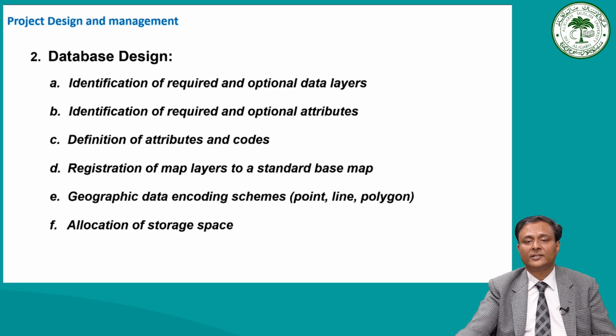The next can be the registration of map layers to a standard base map. In all the spatial information analysis, we try to bring all the databases into one standard format, into one standard base map. So what would be the scale of an existing database, and are those scales appropriate to our mapping scale?